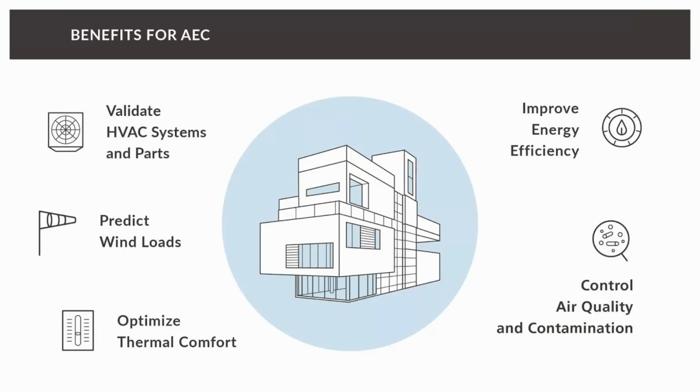And whenever it comes to very large buildings or very tall buildings or very large bridges, methods we use for small buildings are not valid anymore. And there it's a really cheap alternative to wind tunnel testing, not only because it's cheaper, but also because it provides us much more information than a wind tunnel test. And for sure, you can use it, as I mentioned, to optimize thermal comfort inside buildings, or also for the control of air quality and contamination, what we will do today in order to optimize the smoke removal inside the parking garage.